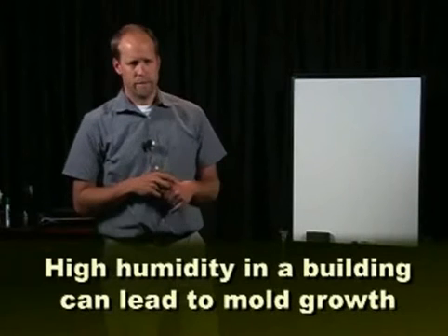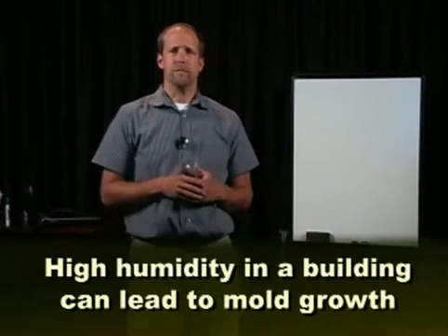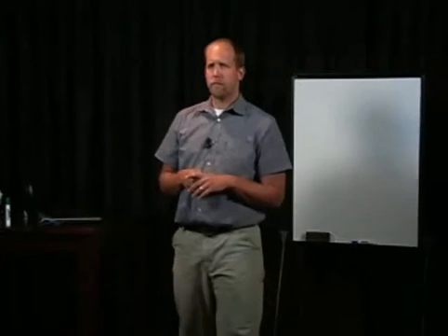Humidity. An inspector should measure the humidity when performing an examination of the building. It's not required; it is at your discretion. High humidity in a building can lead to mold growth, so humidity gauges are very useful. When a high humidity level is measured inside a particular area of a room or building, the measurement may indicate hidden mold growth. Further evaluation is needed when high humidity levels are measured and mold growth is not visible.